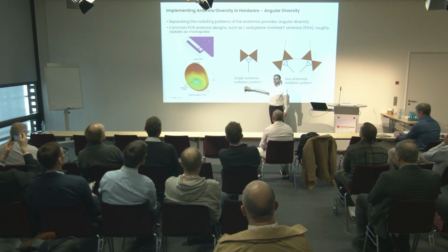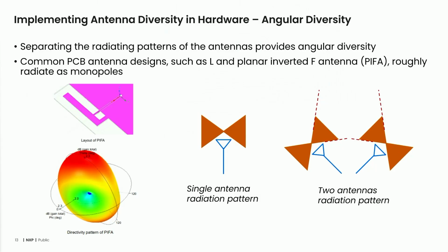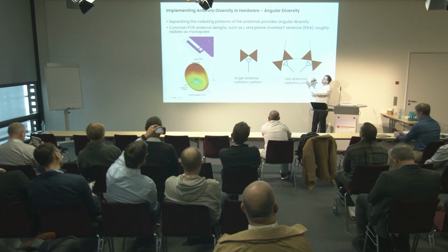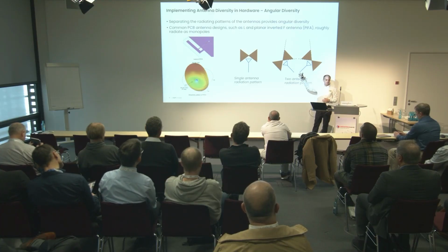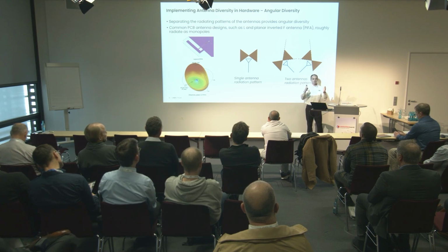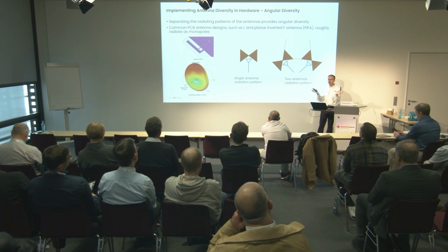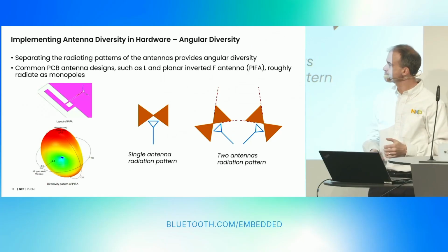And this is just for visualization purposes. Obviously, it's a pretty crude representation. But if we have 2 antennas and we angle them, our coverage of those 2 antennas, because they're angled, is much, much greater. And so that's why you'll see on the PCBs that they're not only spaced out, but the antennas are angled at a particular angle to maximize the coverage of that radiation pattern.